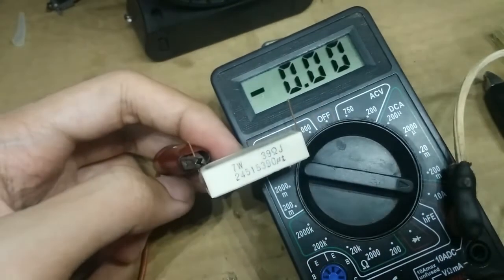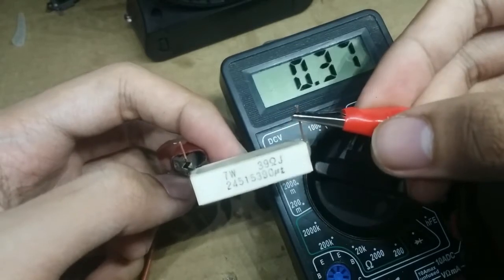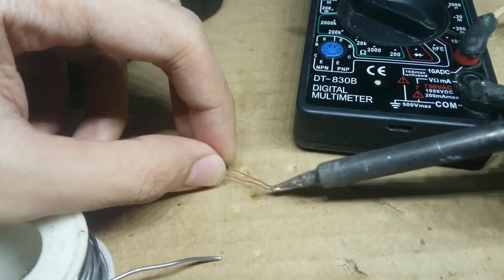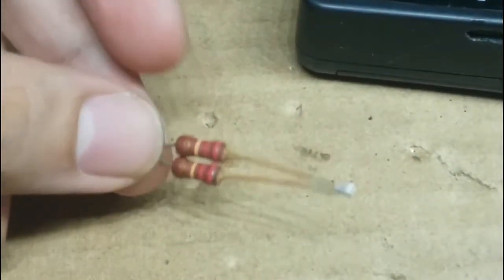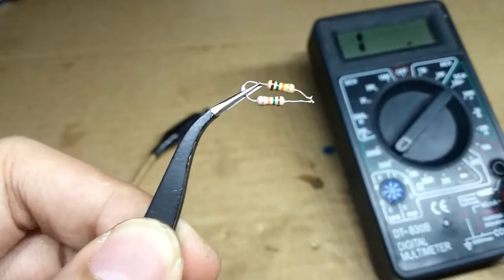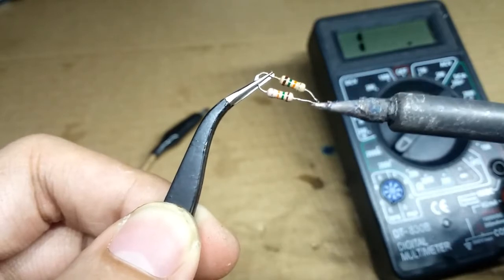Speaking of power rating, you can add the power rating of the resistors if you connect them in series or parallel, but commonly you will connect resistors in parallel that have a similar resistance. This will add their power rating. Connecting resistors in parallel will decrease the total resistance.